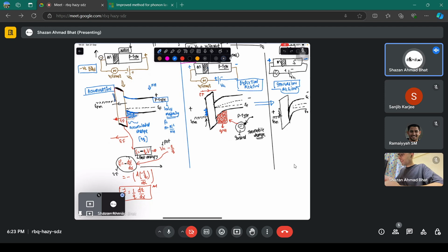So what happens is that electrons start to get generated. The generation-recombination mechanism now becomes dominant. They come from the bulk material itself. So now electrons start to get generated, with breaking of the bonds inside this semiconductor, and it generates those electrons. It is as if you had these ions stay there after the depletion. This is the depletion width, similar to that of a p-n junction, made by these depletion charges. Now what happens?